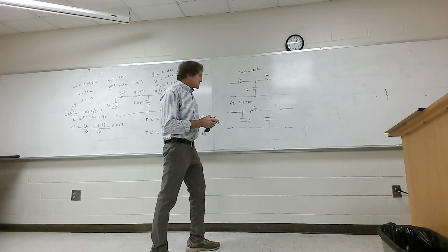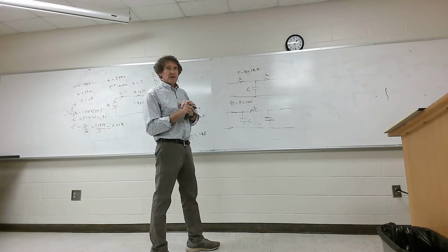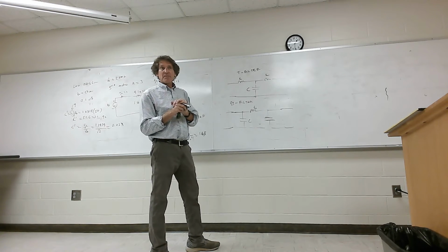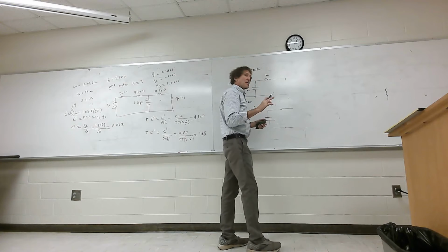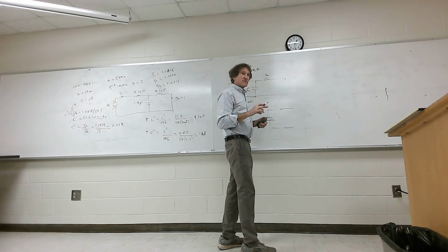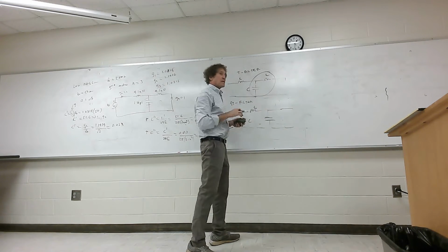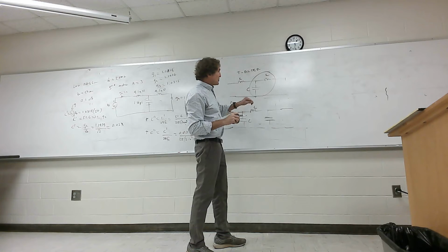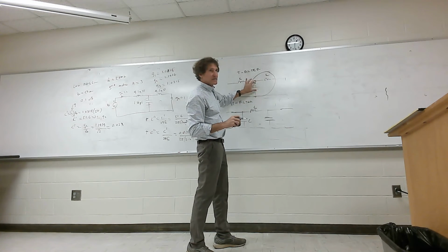There is one thing he doesn't talk about with these type of filters, and I think I mentioned it earlier. Anybody remember one problem? All right, if this impedance is very high, or you're going into something like an FET transistor with a very high impedance, then you have a resonance circuit formed there. And at resonance, you'll get very large voltages developed here and here, and it can break down this capacitance.